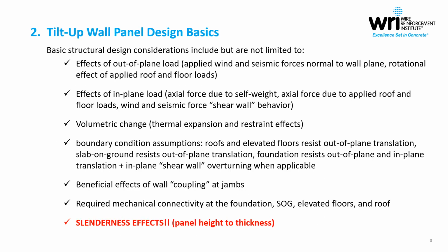As we move into panel design, there are some basic considerations that need to be made. As a designer, in designing a wall panel, you're capturing the effects of out-of-plane loads, so applied wind and seismic forces that are normal to the wall plane, as well as the rotational effect of applied roof and floor loads that might arise from having an eccentricity from the center line of the wall. Effects of in-plane loads, of course: we have axial force due to the self-weight of the wall, axial force due to applied roof and floor loads, and then wind and seismic forces, essentially shear wall behavior.